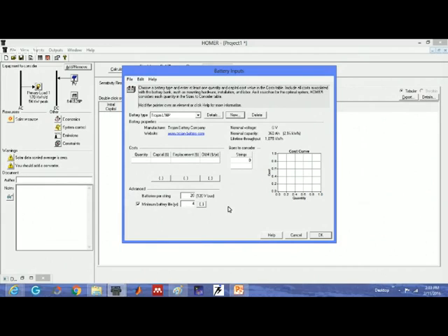It's not like that every 4 years you have to dump your battery. It may be that its life is 6 years, 7 years sometimes, and sometimes even less than 4 years. If there is some damage, then it can go beyond, say, 4 years also. So it's up to you how you choose floating life. It can be 10 years if you maintain the charging rate and discharging rate in level, and you maintain the SOC, state of charge of the battery, within the limit.